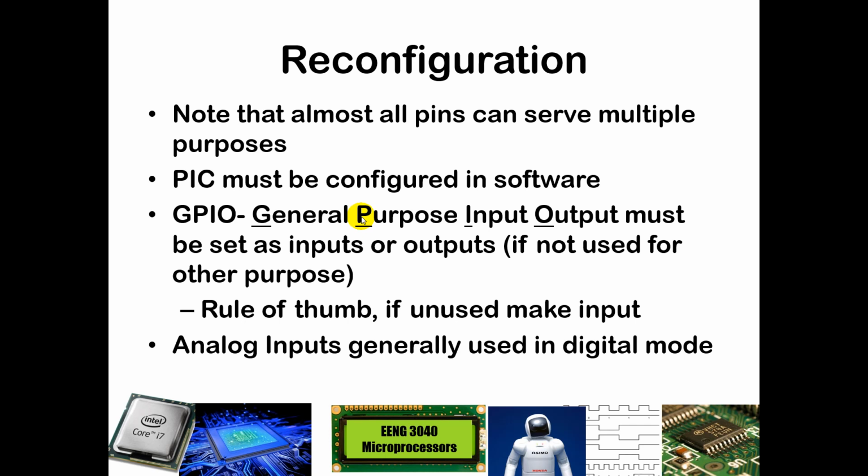But if you're not using them in those kinds of configurations, you can more generally just set them up as a digital input or a digital output. A general rule of thumb here, and we'll see why a little bit later on in this slide set, is if you're not using a particular pin, we want to make it an input.